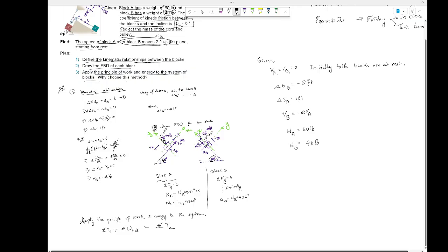No, because this pound is the pound force. Remember that? W is given that way, right? If it's like SI unit, then it could be in kg and you need to find it in Newton by multiplying by 9.81. But if you're going to divide them to find the mass, you divide by 32.2 to find it in slug, if you remember that, right?